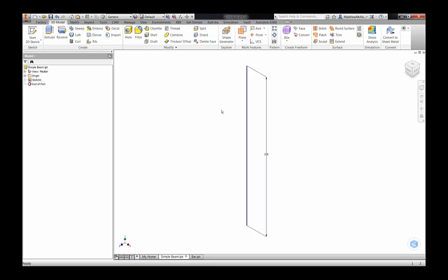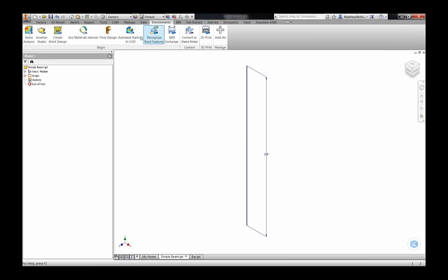and as we often refer to in a lot of these Nastran In-CAD webinars, we really want to simplify our geometry, take it back to basics so we can analyze much earlier in the design process. And this is no different with buckling analysis. So you can represent your geometry as sketch elements and then assign geometry to them. And that's exactly what we've done here. So I've got a simple sketch that's 250 mil long on a plane, and that's really all we need.